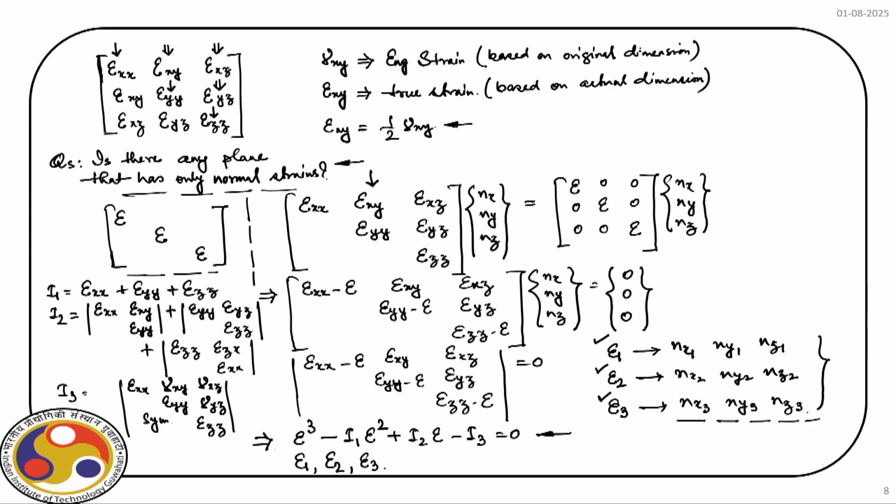Now, for strain analysis also we can draw the Mohr circle, and from that Mohr circle we can again find out maximum shear strain. Now, if you look at the definition of the principal strain, these are the strains that have no associated shear strains, but the plane where we will have maximum shear strain, again we will have some associated normal strain, right.